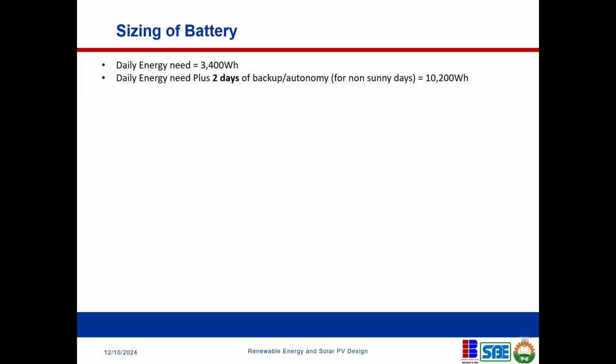But when you're doing your design, you don't assume that the sun will be out there every day of the year, 365 days. You don't make that assumption. You also assume that there could be days when the sun is not going to come out. It can rain all through the day. That does not mean that the solar will not produce. It will produce at a minimal level, correct? But again, we assume that it's not going to produce anything significant to serve the load for that day.